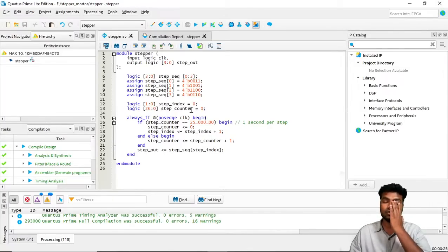And then I want to share one thing. I received a query about why UART doesn't use a clock. Why can't we use a clock for UART? Because if I am using a clock, the transmitter device and the receiver device must both have the clock to make the synchronization. So this is a big reason why we don't use the clock.